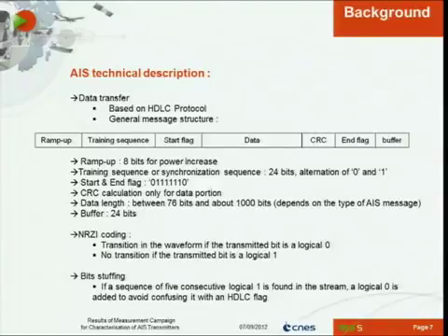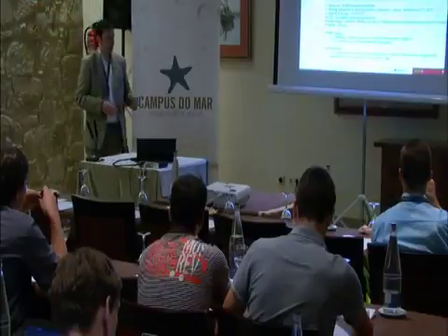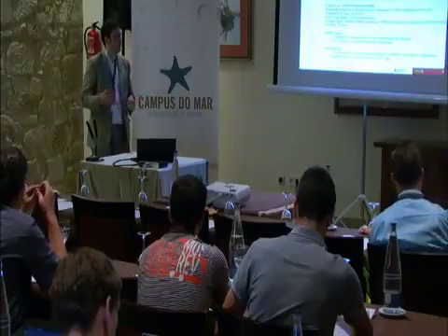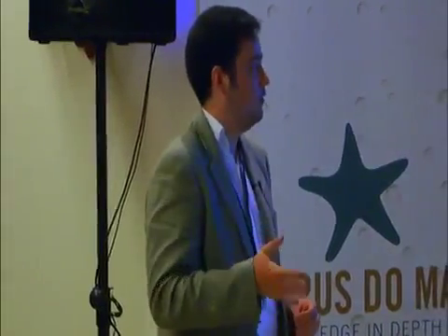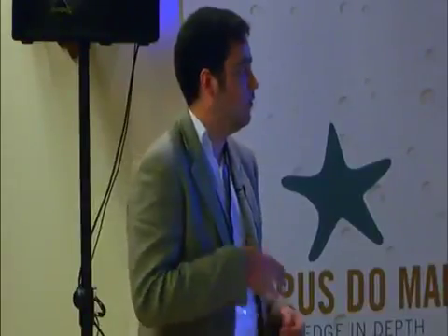The used coding is the NRZI coding. So we have a transition in the waveform if the transmitted bit is a logical 0, and no transition if the transmitted bit is a logical 1. The bit stuffing is used to avoid confusing a sequence of bits with a start flag or an end flag. So in the useful data, if we have 5 consecutive logical 1, a logical 0 is added.